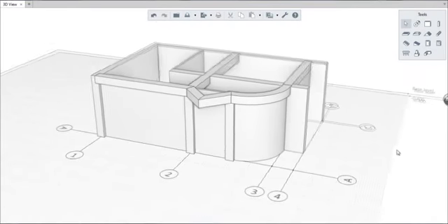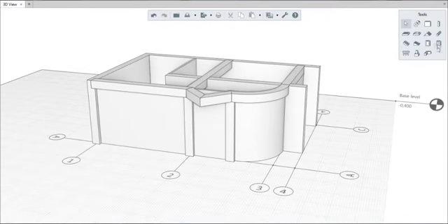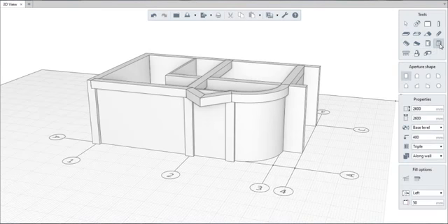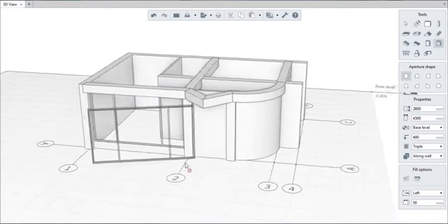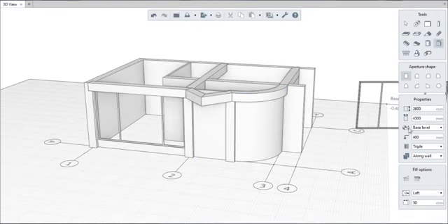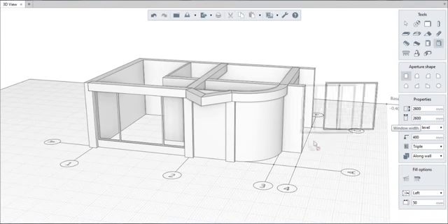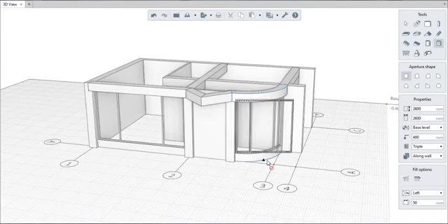For the interior of the townhouse, to get light from the outside, windows should be added. To draw the window, use the Window tool. Set its height to 2600 mm, width to 4500 mm, and height from the base level at 400 mm. Set the window's type as triple. Snapping to the center of the wall, insert the window into the wall. Before inserting a window into the arc wall, change the width of the window in the Properties panel.